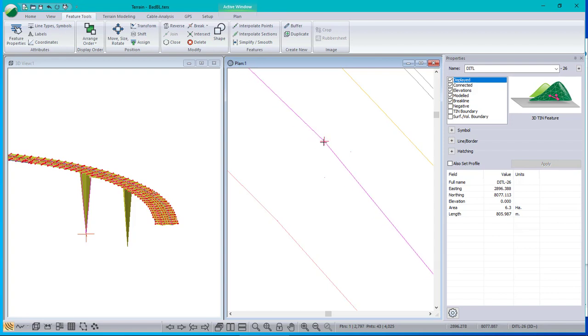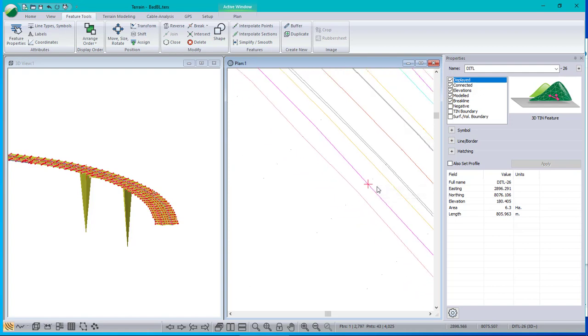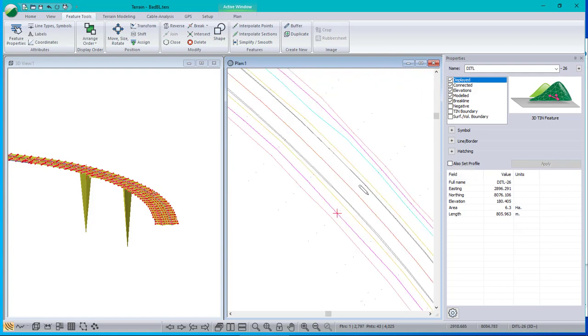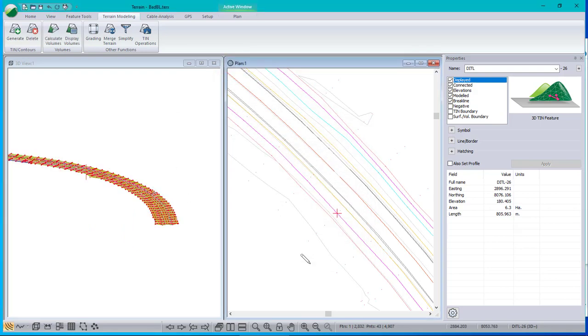So I'm going to pick up this ditch and snap it to one of those points. They're all the same, doesn't matter. There we go, 180.4, and that seems reasonable because the next point is similar and the previous point is similar. But I am really just making stuff up. So now if I build the model, let's skip the contours. Those stray points disappear and I now have a reasonable surface.